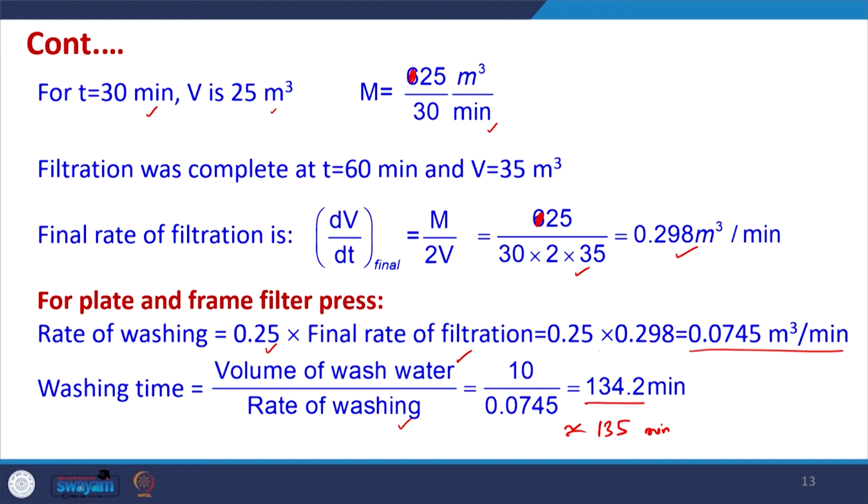and so, as for the sedimentation basin, here also generally we can have 2 or more filtration units in parallel. So, if 3 are working, one may be in washing mode. So, this way we can always have continuous filtration going on, because out of the few units one has to be washed. So, this is also another design criterion that has to be taken care of whenever we are designing any filtration unit.